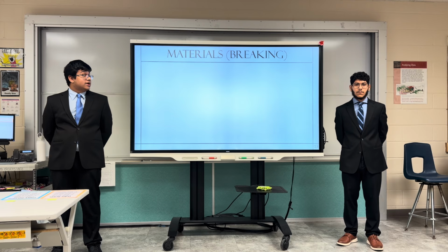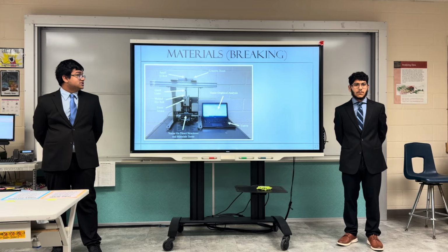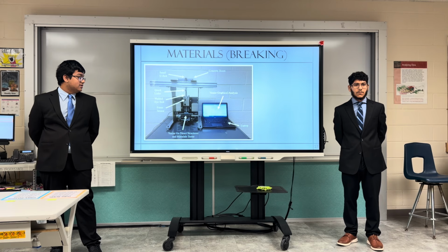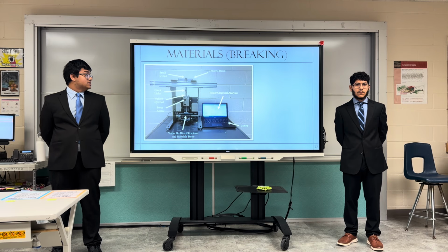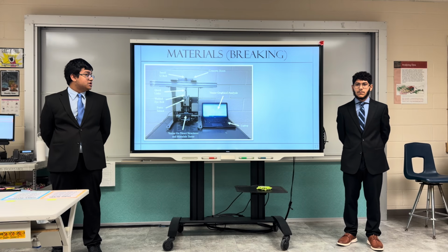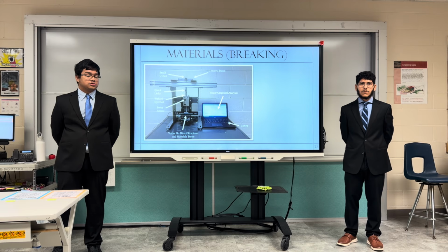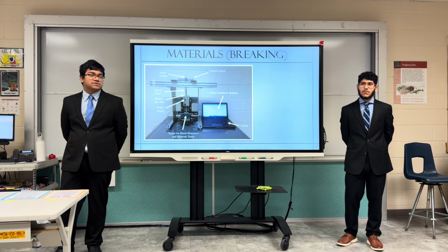Next, we'll go over materials for breaking the concrete. First, we have, of course, our concrete beam, which is held in place by a small U-bolt in the Vernier materials tester. This U-bolt is connected to a force sensor by quick links and welded eye bolts, which, once the concrete beam is broken, the maximum force withstood will be measured by the Vernier Graphical Analysis app on the laptop.